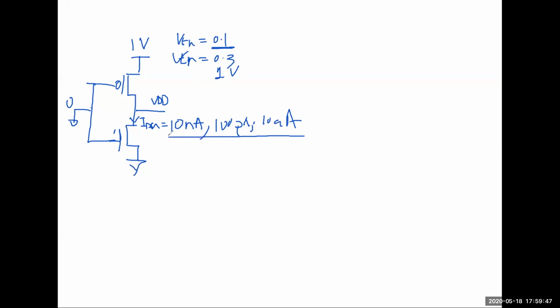And this is called the leakage current. Even if your gate is off, because your VDS is large because of the high field, you just have leakage current. So that's the other reason, actually, at least for a couple of the analog blocks, when we use digital, we use high VT to make sure, if it is really low power, we operate at very high temperatures and high voltages, then we choose the high VT because this leakage current also will drop.